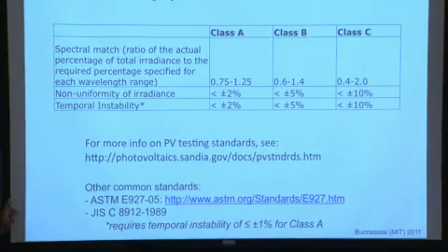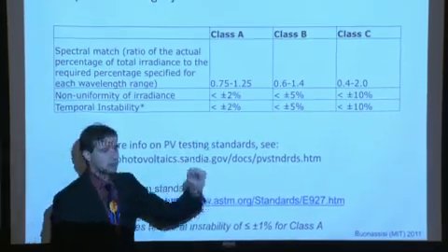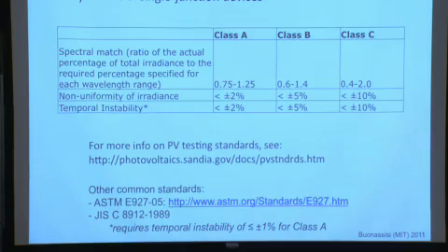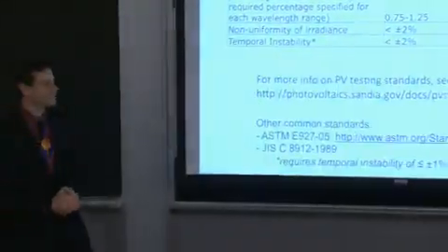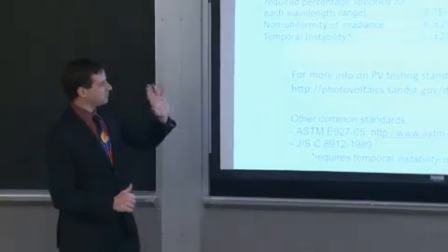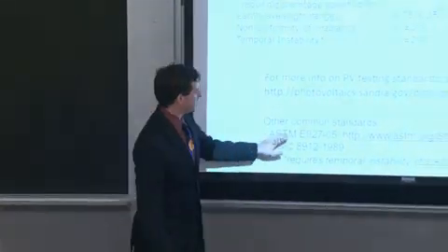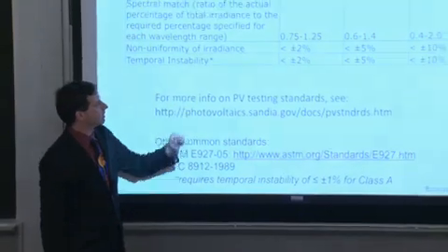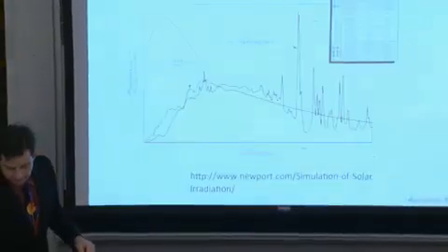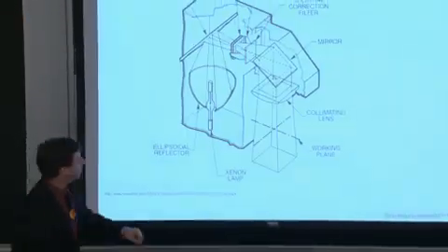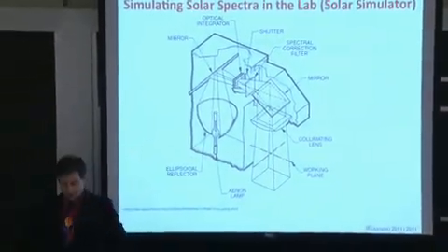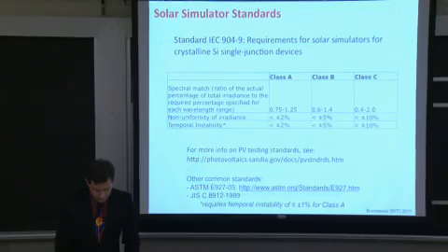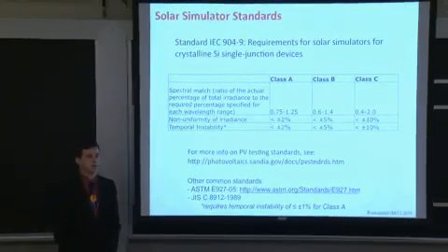The solar simulator downstairs in building 35, in the laboratory that several of you saw yesterday when you did the phosphorus diffusions, I poked my head in and saw everybody there. So about a dozen of you might have walked past the solar simulator in the laboratory. It's a large area, as in the illuminated area at the working plane is around 20 by 20 centimeters squared. And it is a class AAB solar simulator.